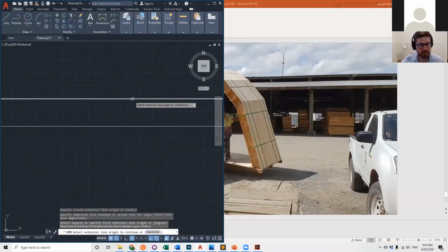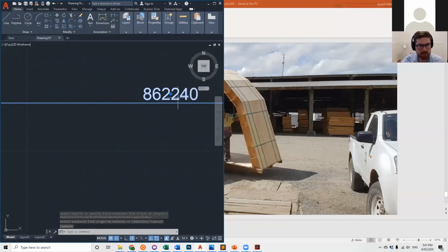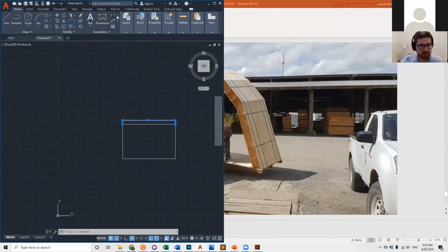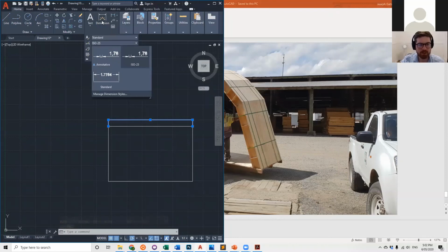It will be linked to your template. So you can see here that I'm drawing in a dimensional template, but the scale of this is not appropriate to the font size. So this is an 862 meter long thing, and that's probably like a 12 mil high font. So the fonts are drawn exactly to relative scale. If you want them to adjust, you'll have to draw an object at an appropriate scale or adjust your template and annotation size. I don't know how to do that directly, but it'll be in these settings somewhere.